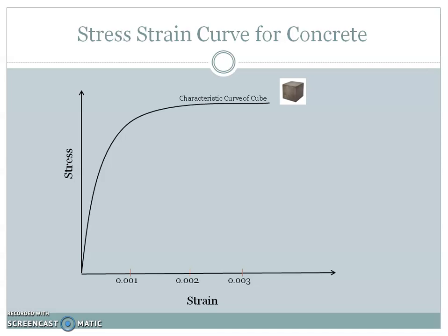But as you are going to design the concrete for the full structure, the compressive strength gets reduced due to the influence of the size of the structure. When we cast 150 by 150 by 150 in the lab, it's a very constrained environment, so we can take care of each and every minute detail for the concrete. But when it comes to designing the concrete for an entire structure, due to its size and due to site conditions, there can be slight variations which are seen.